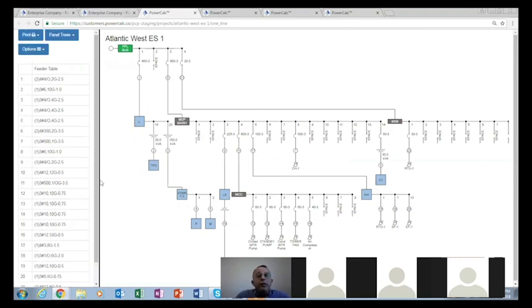The other option is that some municipalities, especially here in Florida, will not accept it unless we have the conductor size next to the conductor representation for it. So we have an option here, you go to option, hide the legend. And I also have an option here to change the font size if you want to.